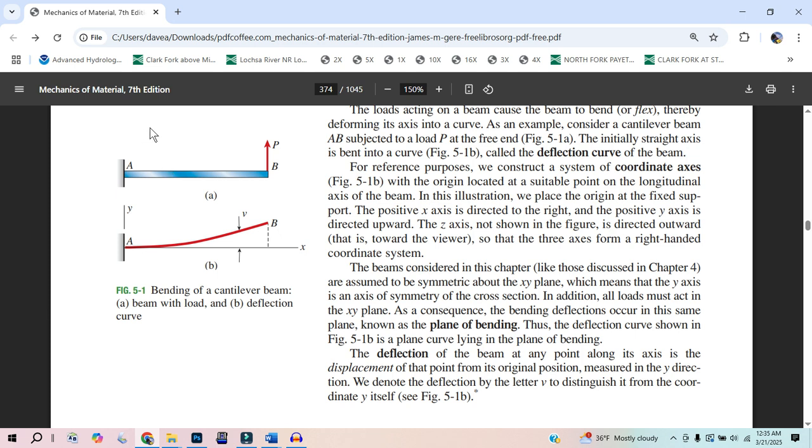I have to rack my brain for, because that's the later part of this video. What happens is you have a square, and let's say we have a downward shear on this side, and an upward shear on this side. So that's going to be a positive shear. It's going to go this way. That's going to be the opposite of this scenario. But then if we look at that square, we got a downward and an upward. And if it's in pure shear, there's no moments. We have to have a shear force this way and that way. And so those two shear forces are causing it to rotate the other direction.